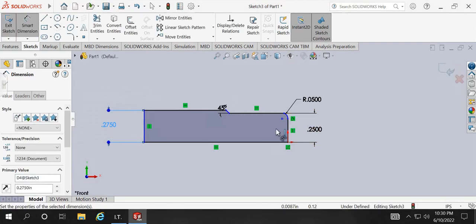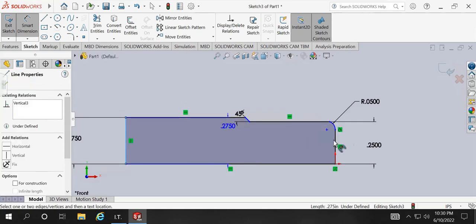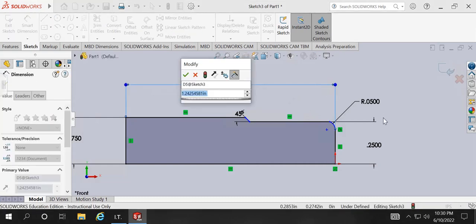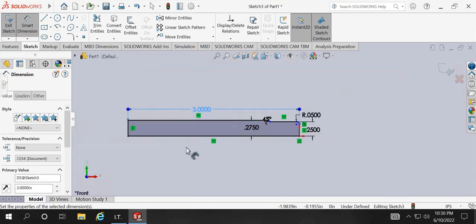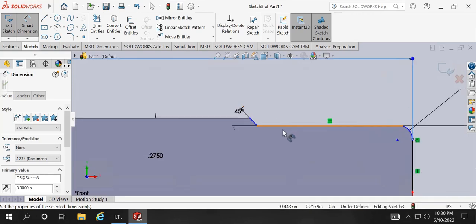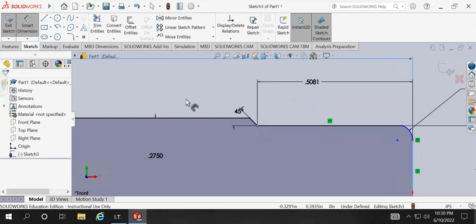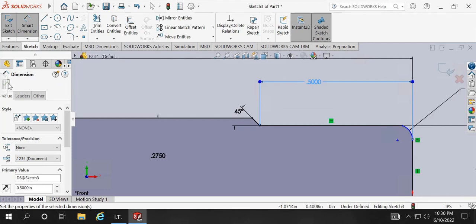anything more than that tool diameter itself. Then the total length of the tool from the origin itself generally is like 3 to 4 inches. I'm just keeping it 3 inches. Well, tool length can vary from anywhere from 3 inches to 4 or 5 inches. And what we can do is we can also specify the length right here. So I'm going to specify that, okay, 0.5 is the length that I want to work with.